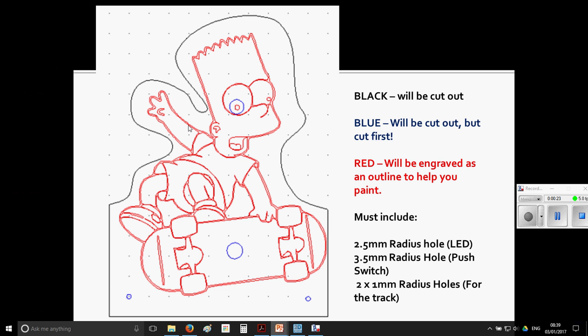What you're going to be doing in today's lesson is starting to design a backboard for your Steady Hand Game. So your teacher should have shown you what this part will become. This is basically just a decorative bit made out of plywood. We're going to use a CAM, Computer Aided Manufacture laser cutter machine, to cut all of this out of 4mm plywood and to cut the holes and to engrave an outline that you can then decorate and paint. Right, and this will make a really nice quality box.